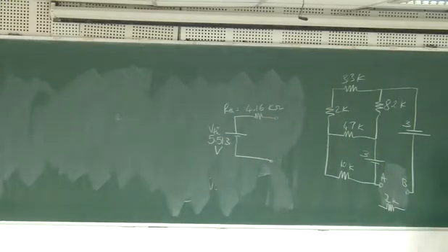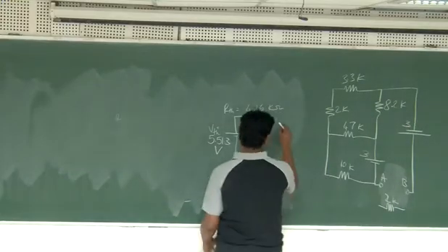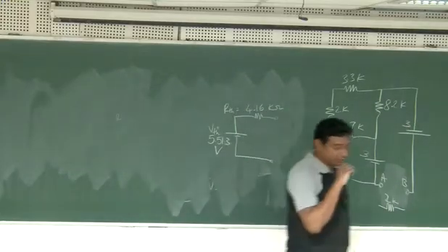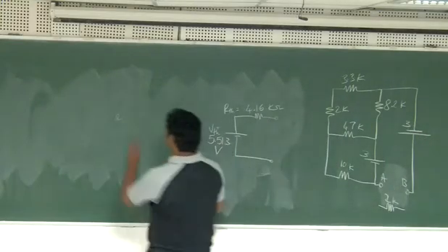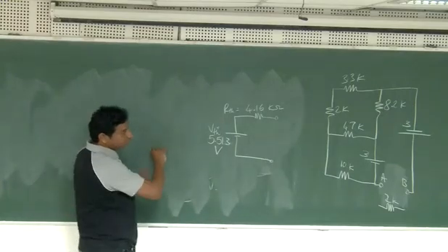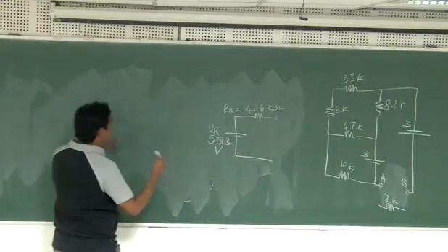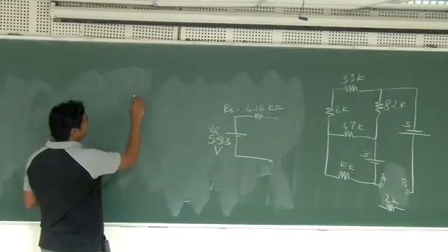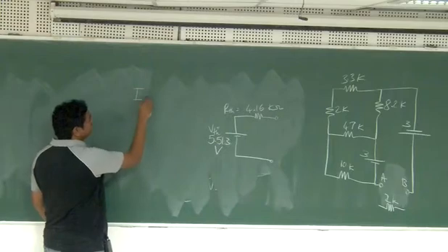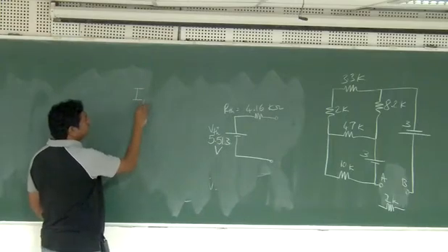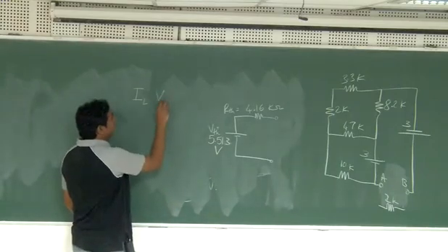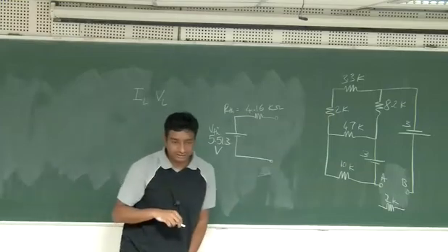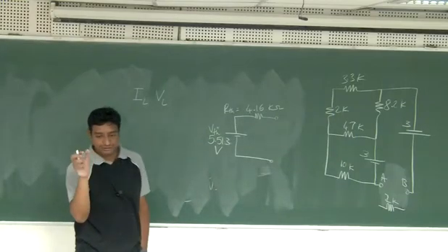Okay, now what I want to do is I want to measure the power. So how to measure the power? So what we'll do is we'll make a quick table like this. I'll not do it on board. I'll just do it on this one, because it's a bit of calculation. But just I'm giving this one. So what I want to do is I want to measure the current in the load resistance, IL. Okay, and I want to measure the voltage of the load resistance, okay, for different values of R.